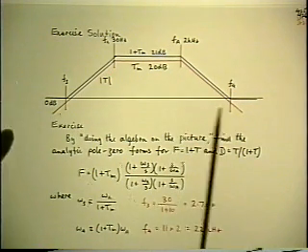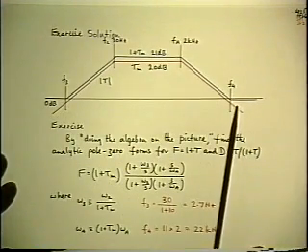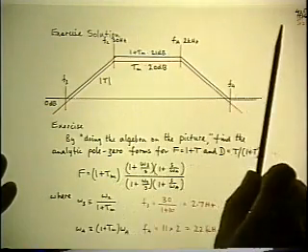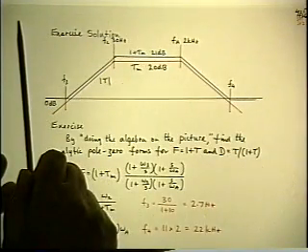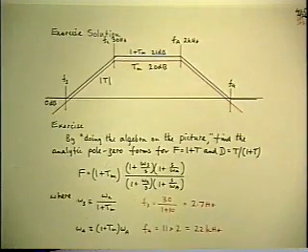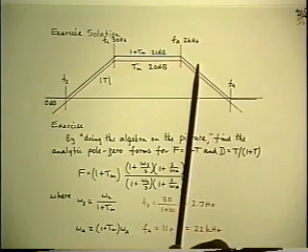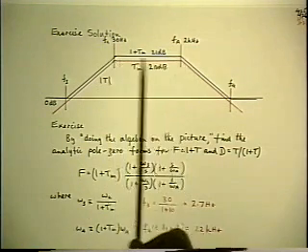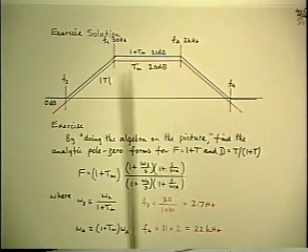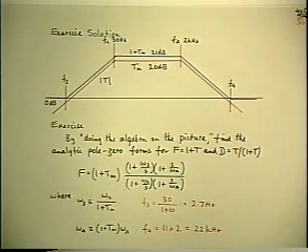So when you do this graphical construction, it's obvious without you even considering it, that the construction that you've done for the top end can simply be matched by the same construction at the other end, and they won't interact. Notice that the non-interaction applies to the two zeros and not the two poles. There's no approximation to do with how far apart the two poles are. It's only the zeros, because they are the roots of the quadratic that you're approximating.